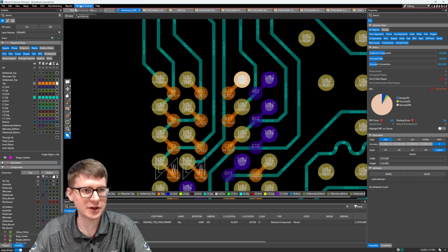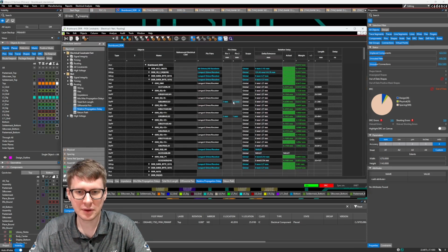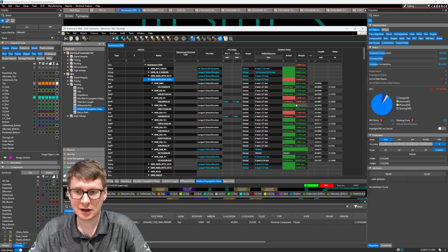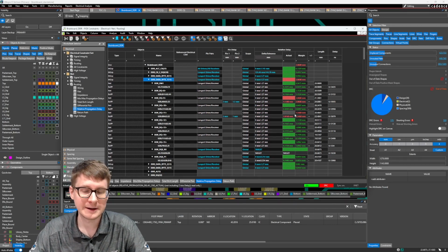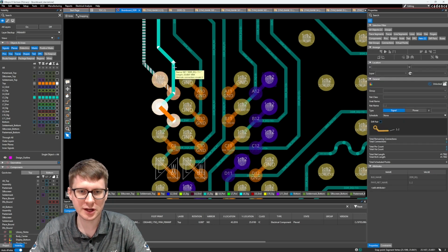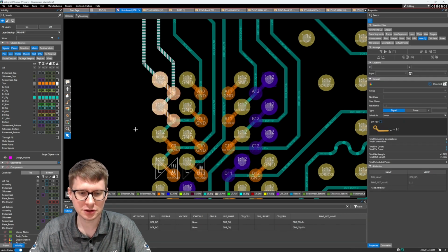So let's go ahead and close that, launch our Constraint Manager again. And here we see that these pin delays have automatically been added into our Constraint Manager, right? We can rerun this entire byte lane and see that now these two nets are no longer in sync, right? The other option that we have is, if I turn on my nets option here, and let's search just these two nets. So I'll highlight them, right click, show in search results.